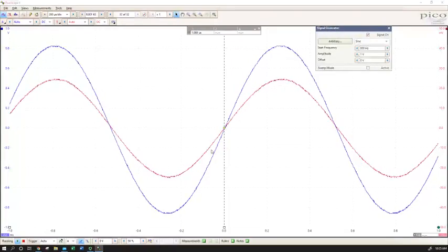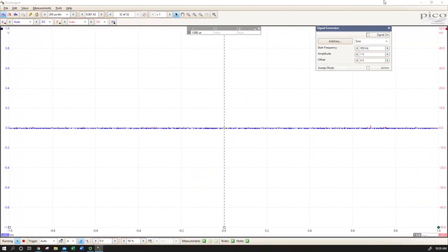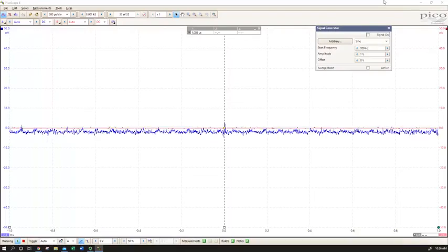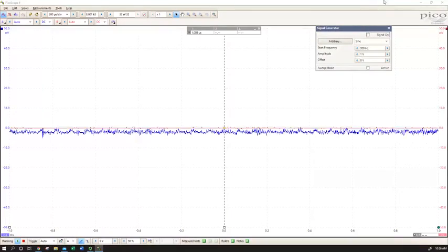We can put in 47 times 10 to the minus 9 for our C, and then solve for L. So it's just algebra. And if we do that, we end up getting about 0.6 henries for the inductance value. So that's 6/10 of a henry. That is a reasonably large inductor as protoboard type inductors go. In fact, in my kit, my largest value of inductor is 100 millihenries. So I now have the option of something 6 times that size if I were to need it.